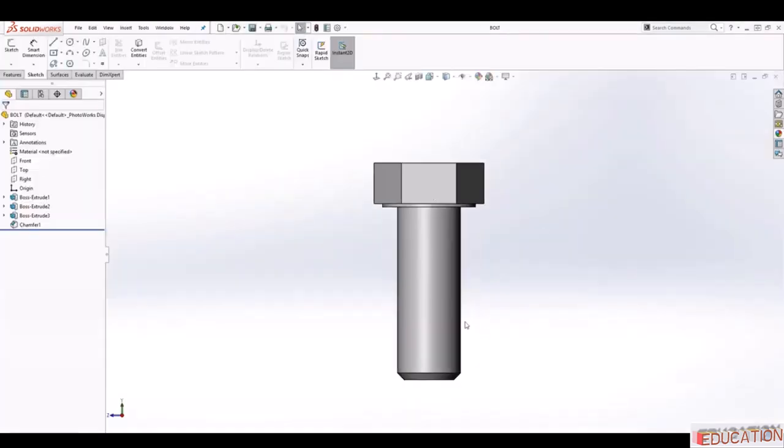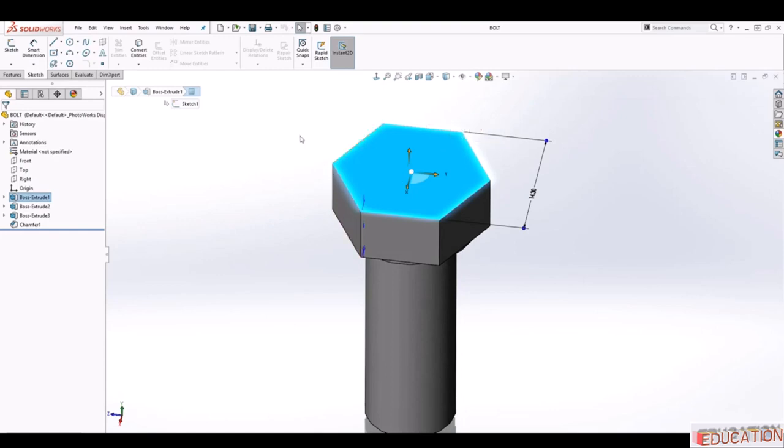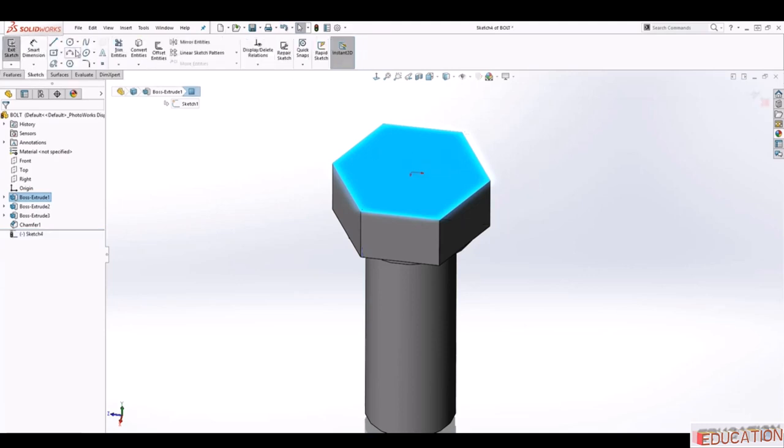So now you have this bolt. For this bolt, what we want to do is cut the threads on it, and also cut the chamfer on the top. So to start, the sweep cut tool also works just like the sweep. You always need a part and a profile. So we'll create our part by selecting this top face and adding a sketch to it.